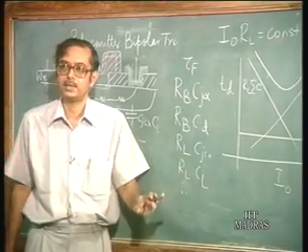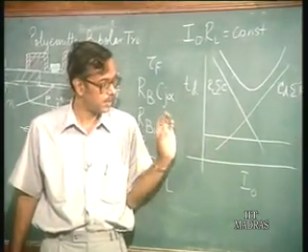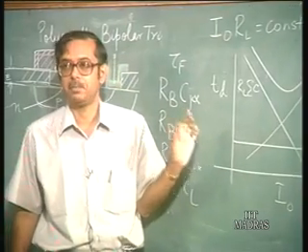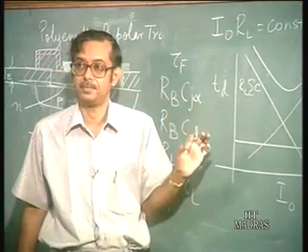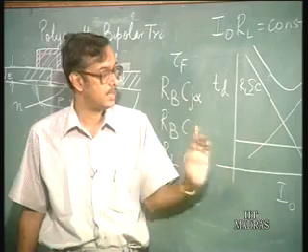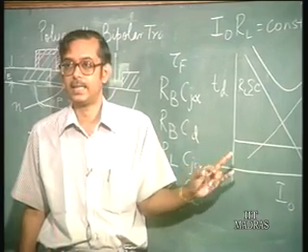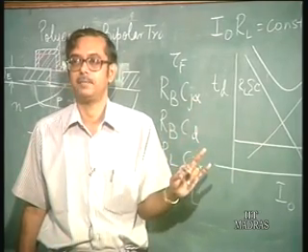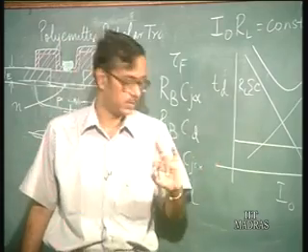So the point is, the delay is not independent of I naught, but there is a minimum, and the ECL gate must be biased at that I naught to get the minimum delay. So, we shall stop here today.